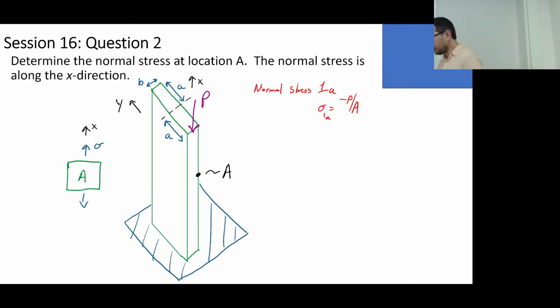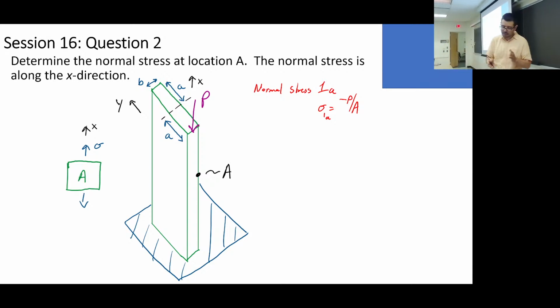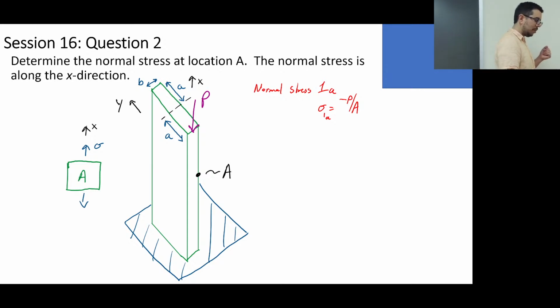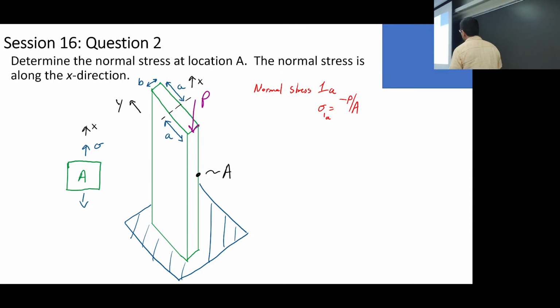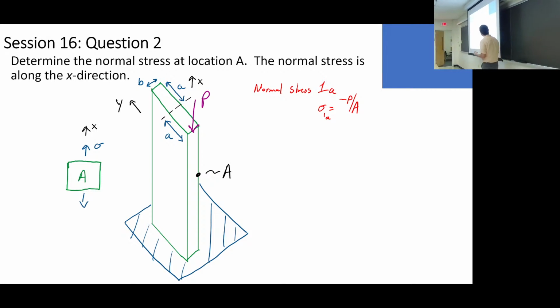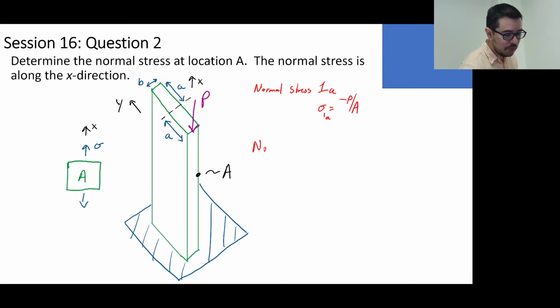I think you're also kind of thinking, well, if I do it off axis, or if I was at the middle, maybe it's almost like a double shear situation. That's not really what we're getting at here, okay? If you have a double shear or something, maybe you could induce a shear force and a shear stress directly, but no, we're not really going for that, okay? In this case, we've eliminated this transverse shear stress, and also another thing to point out is that we're only asking about normal stress. So how does the location of P affect some normal stress, we'll call it 1B. Okay, so you've got one normal stress already, but I'm going to tell you that there's another normal stress. Let's call it 1B.